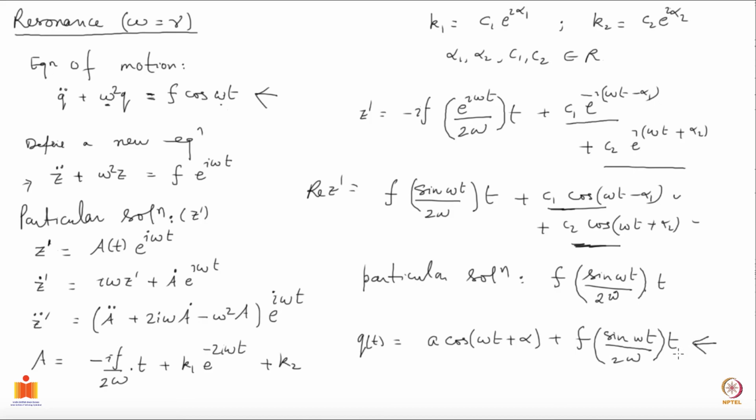So at some point of time the displacements will be large because as time grows the displacements grow linearly, and your approximation that you are close to the equilibrium will no longer hold true, and all the other terms that we have dropped in linearizing the equations of motion would play a role, and this solution will not be valid.